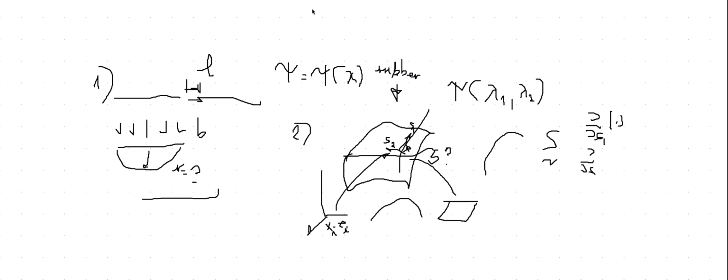So just to give you a transformation, I can go from local to global into this one here, and basically I can establish very easily this one to that one, and I can establish very easily this one to that one. This happened to be only rotation, so this is your orthogonal tensor Q, and this has to be done with the isoparametric mapping. So what I need, S of psi, will be obtained as a composition of these two mappings. If I want to go from here to there, I can either go from there to there and do the composition of these two mappings, and I get my result. So this is as much as I wanted to indicate.